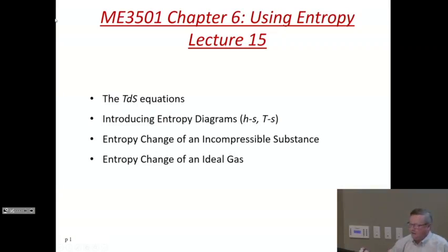All right. Today we're going to go into chapter 6, where we learned how to use entropy. This is lecture 15. It will be aimed at establishing the TDS equation. You'll hear a lot about PDV and TDS equations. With the TDS equations, we will then introduce the use of TS diagrams, temperature-entropy diagrams, which is the equivalent of using PV diagrams, but for entropy.